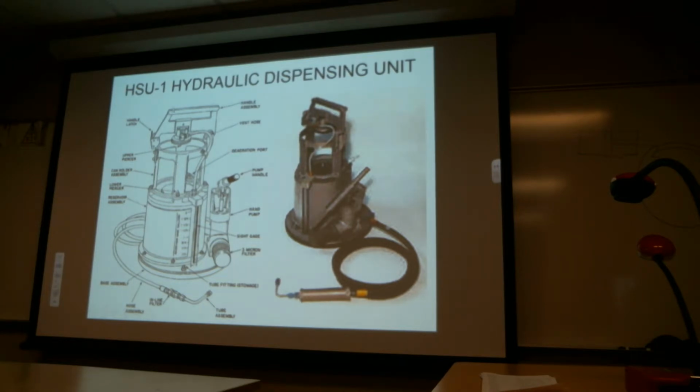And it's got a handle that, again, you close on top of the can, and it pierces the can so that you now have a vent opening for the can. And it's got an integral pump. It's even got a hose and a line attachment with a filter on it. I think it's a 3-micron filter or so. But in any event, it provides so that you don't contaminate the hydraulic system with contaminants.